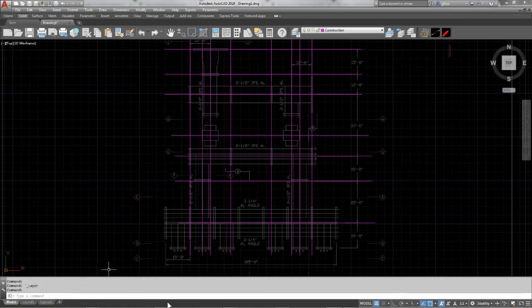And so at this point we're ready to start actually inserting structures and equipment, and this would be certainly equivalent to what you would do in 2D, assuming that you have 2D blocks created for your equipment and your different structures, etc. And if these are all individual blocks, then you would normally begin inserting blocks at this point, and we're going to do the same thing.